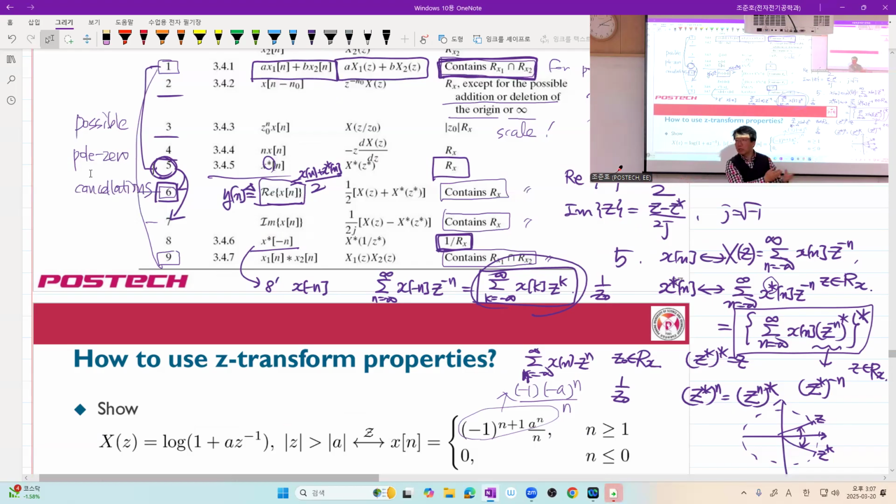So one of the ways is to put some system before, usually before, in that case, so that this pole is cancelled by the zero of your compensating system. So pole zero cancellation can be used to make your system more stable.